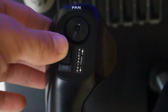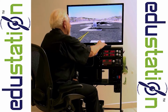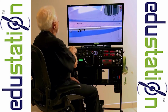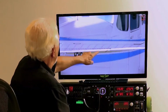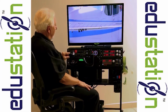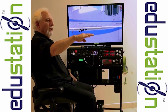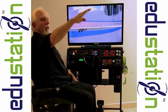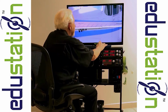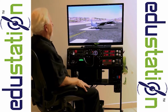Below that is the elevator trim. I'm going to use the plus key to zoom in and use the hat switch just to move over a tiny bit. You will notice on the back elevator there is a small tab, and that tab is adjusted with this vertical switch. What that is doing is making small changes to the elevator so that we can put a plane properly trimmed to fly level and we don't have to hold on. And we'll get to that later. So the plus key, wherever you are, zooms in. The minus key on the keyboard zooms out.